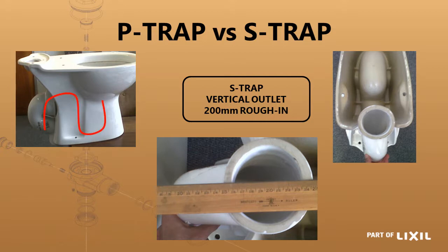As the name implies, it's an S, so if you turn that pan on its side, it's in the shape of an S. That's where the outlet, instead of going through the wall, goes through the floor. So with the Tuscany pan, you can use that ceramic trap. That trap won't work with any of the other pans, but you can use a flexible connector or a PVC connector, which would convert the pan from a P-trap to an S-trap.